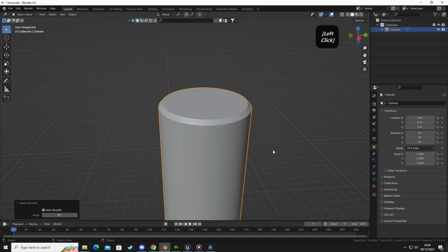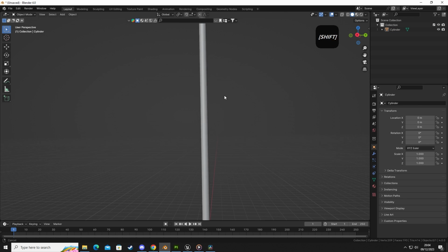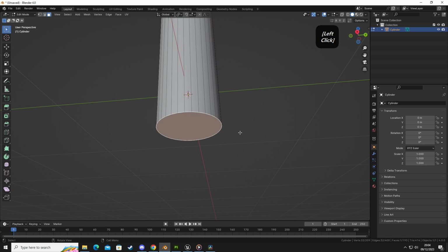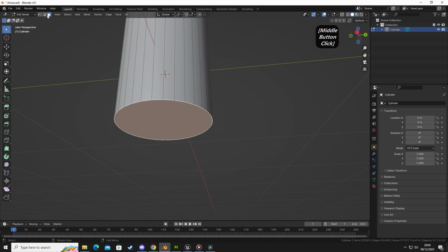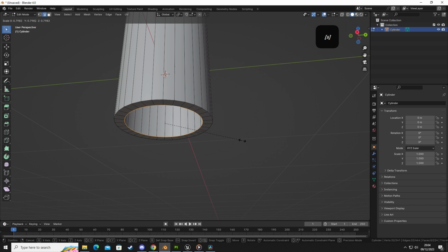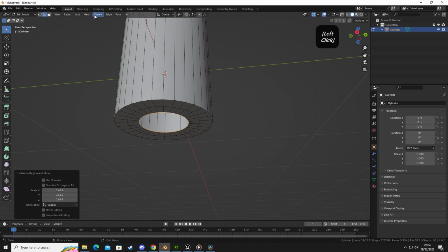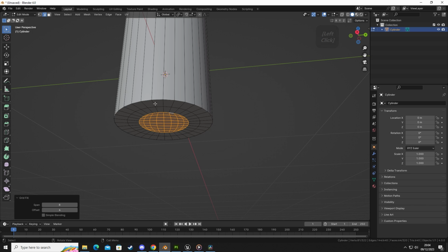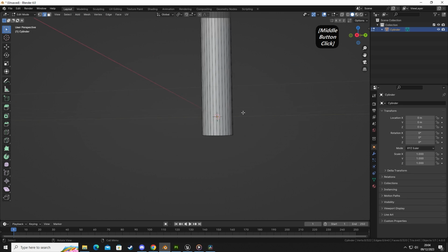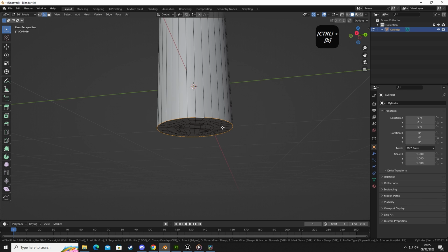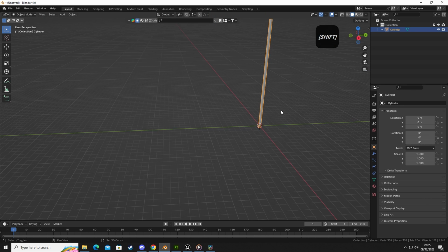There we go. So we're going to auto smooth. I'm going to do the same for the bottom of the flagpole. So edit mode, face selection, select face, X, delete faces, press 2, edge selection, Alt left click, so we're going to select the loop, and then E S to extrude inwards, E S to extrude in, and then to face, grid fill, and then change the offset so it's nice and straight. So you have a nice straight line there. Okay, so I'm going to bevel that edge as well. Select that edge, Control B, give it a little bevel. So now we have a flagpole.